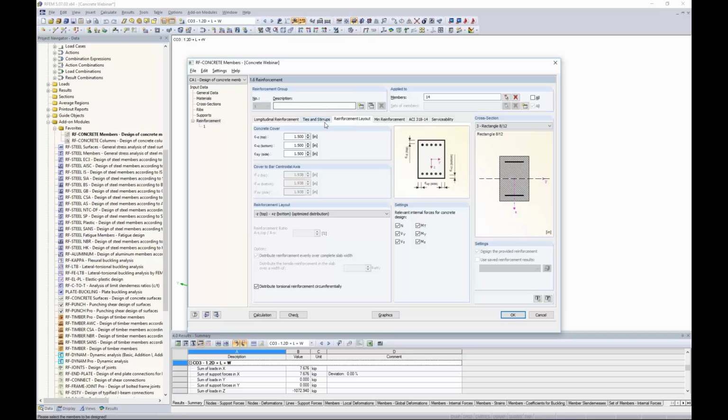Reinforcement layout, concrete cover. This just comes from Chapter 20, Table 20.6.1.3.1. We can consider our concrete cover here. Keep in mind that as I scroll through these, you'll notice that this picture is synced up, so it's kind of nice that you know exactly what you're looking at.